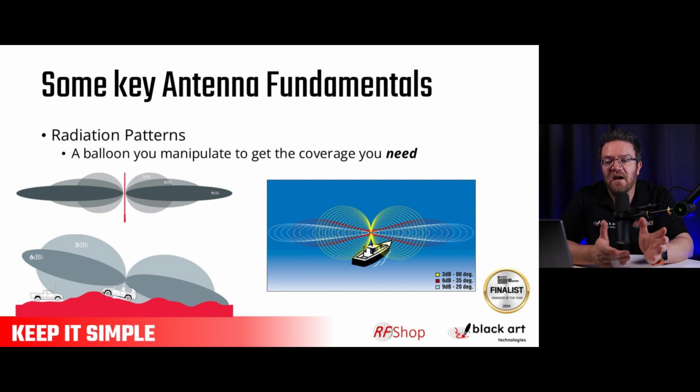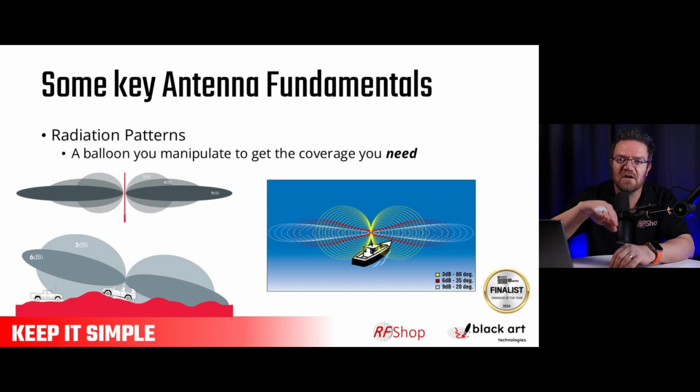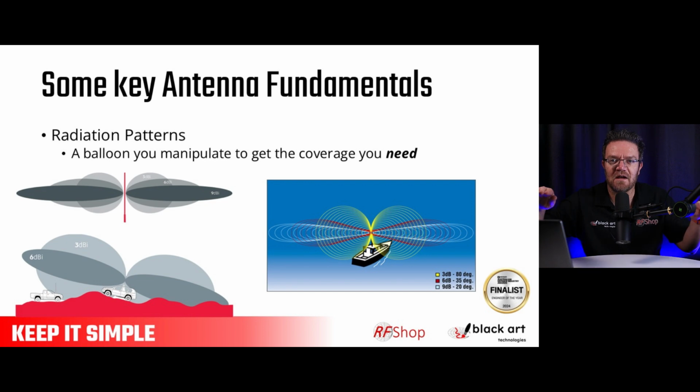You can go for high gain, as high as you want, but the problem is if you're on a slope or driving under this, it's just going up and down, left and right all the time. The high gain antenna has a very narrow coverage on the horizon, and it will constantly miss the horizon, and you'll actually have this sharp slope where suddenly you are at 6 dB gain, 3 dB gain, 0 dB gain. And as you drive, it just jumps around, and it is very jagged, and you'd want to avoid that.